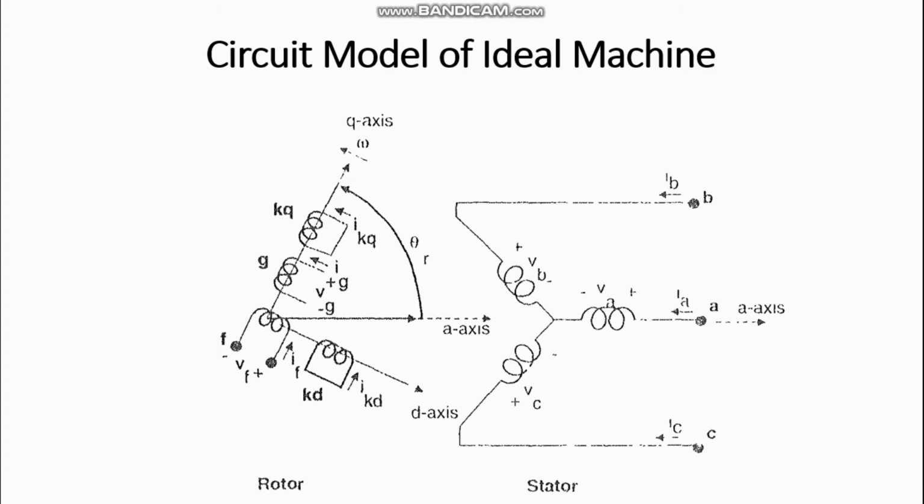Now if you do not allow your rotor to reach a subsynchronous speed, where the relative speed difference between your rotor and stator is very small, the rotor will not be able to align itself with the stator. That is why the synchronous machine is not self-starting. In order to make it self-starting there are many methods, but let us discuss only the damper winding method.